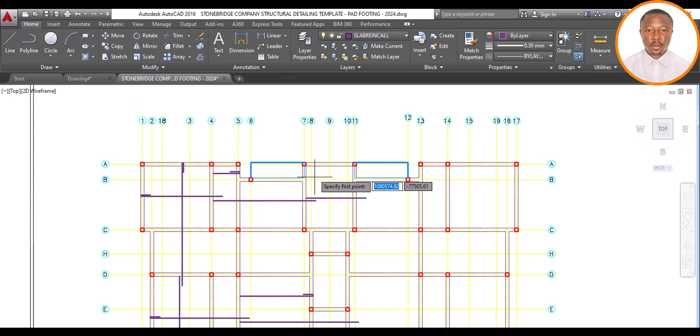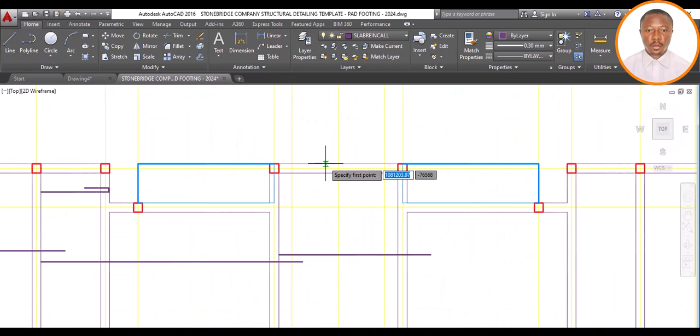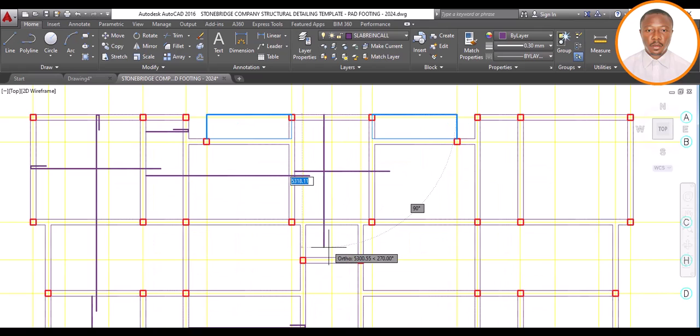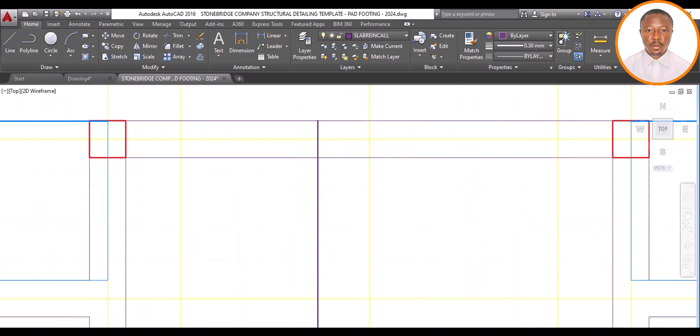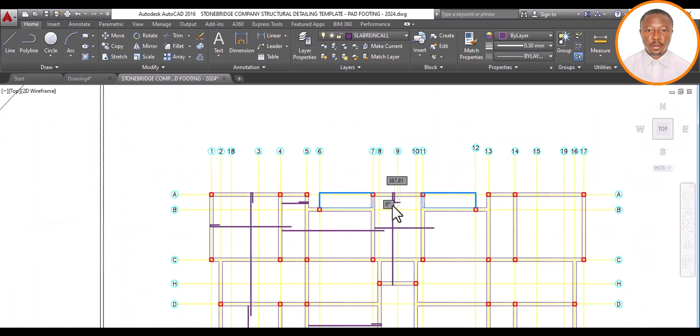So what do we do? Pick our line, which is now my reinforcement. I call it my own reinforcement now. Start from there to this. If I want the same thing that it runs, yes, it runs. Let me bring it here, and then at this point I have my concrete cover from here, 25. Enter. Then pick my line. Then at this point, I have my reinforcement thickness 600. Then I have my return bar as what? 600. Good. So that holds that beam back.